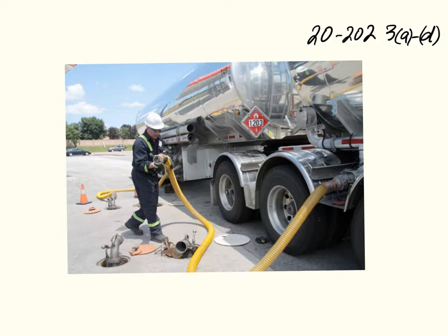Now, when we look at bottom loading, which is kind of an example of what we're looking at here, there is a Zone 2 location essentially all around the part where the fluid comes out. So if we draw that in here, what we're really looking at, if we did this, we have a semicircle like this, and that extends, again, we're back to that old measurement of 900 millimeters either way.